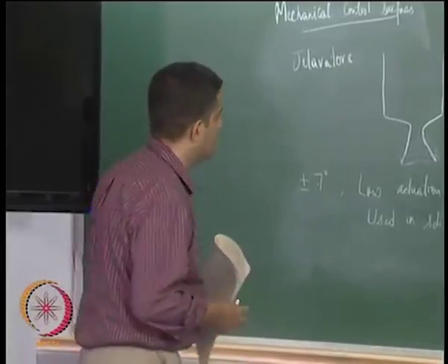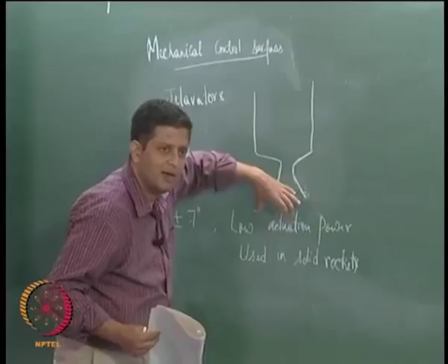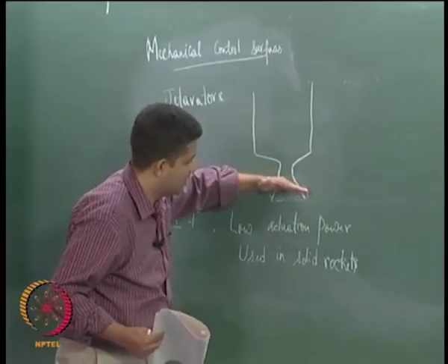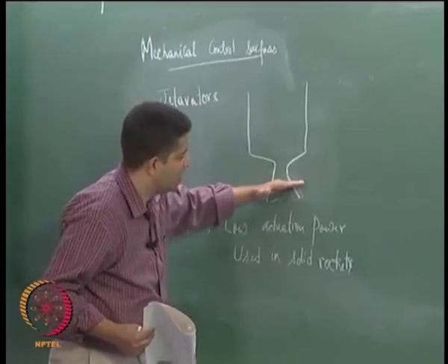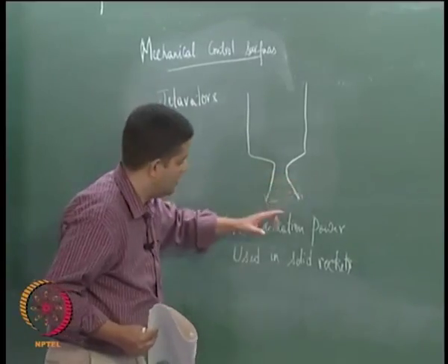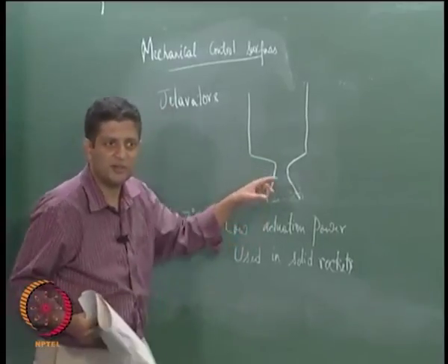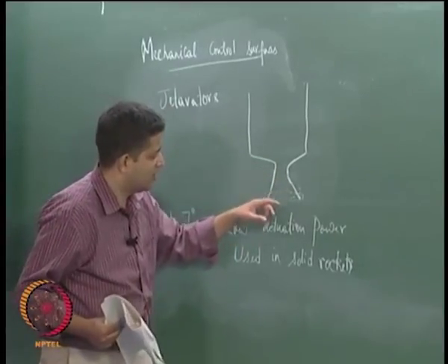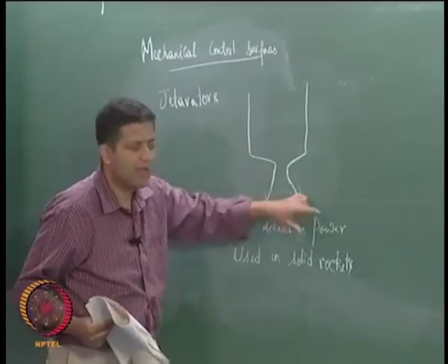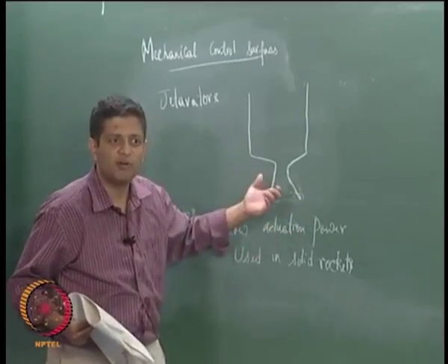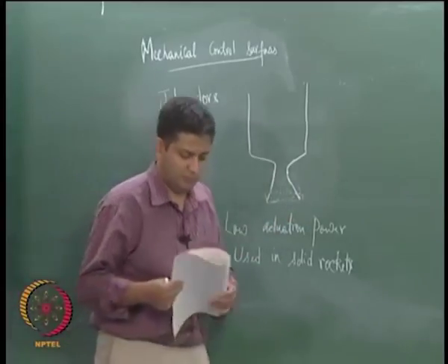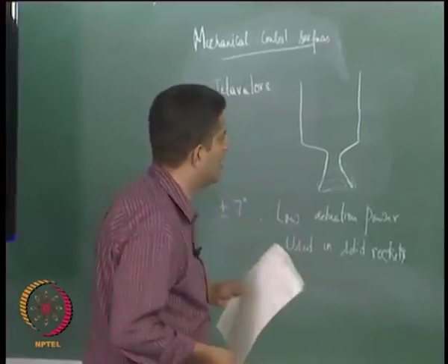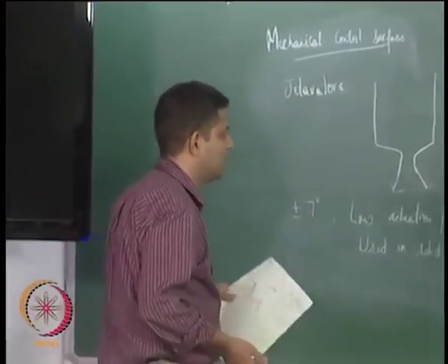Yeah. Which part is rotating in this? This small portion, this dotted line, it is in line with the nozzle when it is not doing anything, right. You can then rotate it, and on one side it will be flush with the nozzle. So on one side it will over expand, and on the other side it will under expand, and therefore give you the required side force. Okay. Then there are some things known as jet tabs.